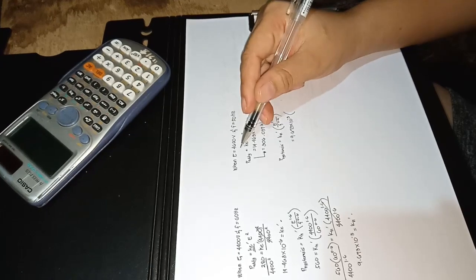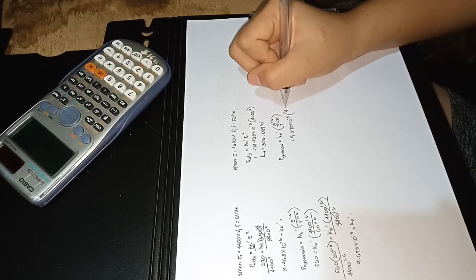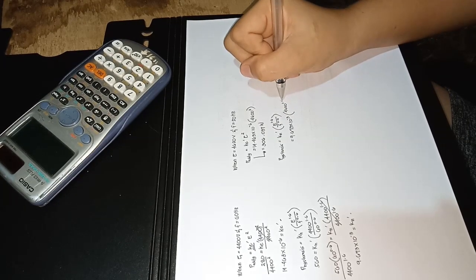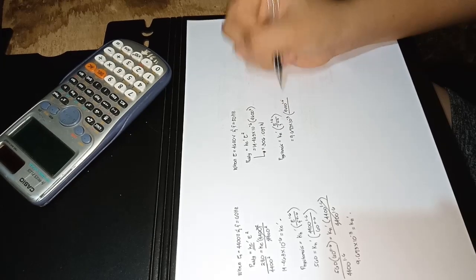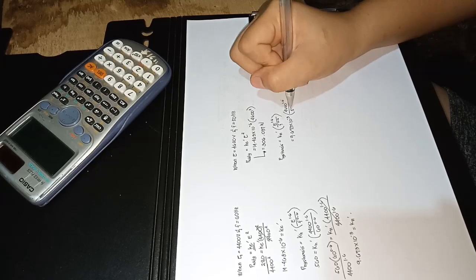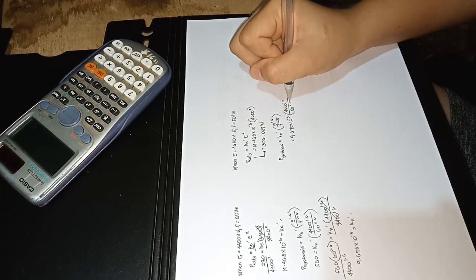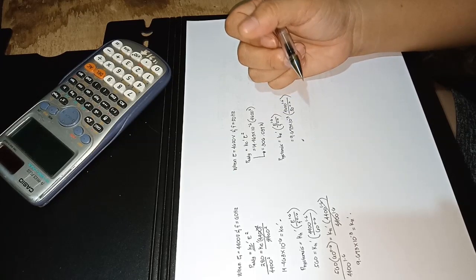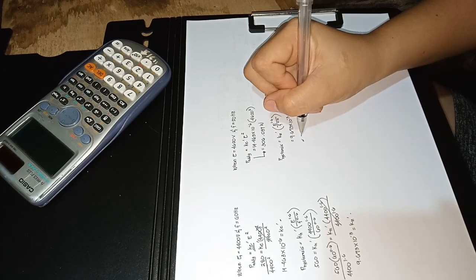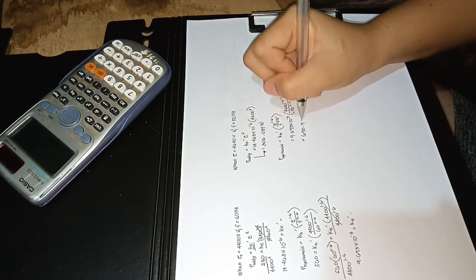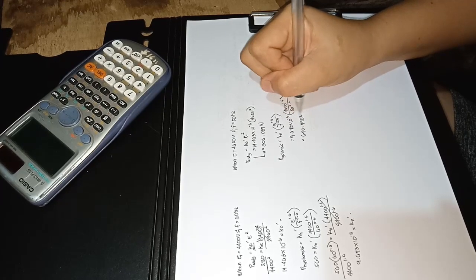Use 4,600 as the value of E raised to 1.6, and f of 50 raised to 0.6 equals. So the hysteresis loss is equal to 670.798 watt.